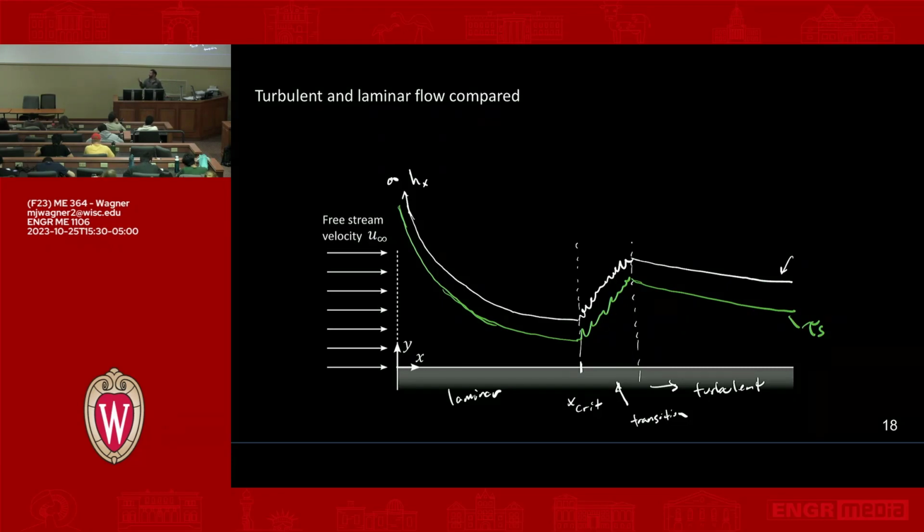So turbulent heat transfer, takeaway, if you remember only a couple things of what I'm saying, which is probably what will be the case: turbulent heat transfer is better than laminar heat transfer, except at the leading edge, right? Just remember that. Turbulent heat transfer is always better than laminar, except at the leading edge.